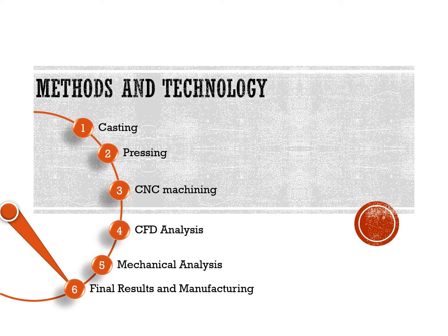Talking about casting, it is a manufacturing technique widely used around the globe for centuries, and due to the complex geometry of the blades, investment casting is preferred for manufacturing the turbine blade. There was also an attempt made by Kathmandu University at single piece casting of the turbine.